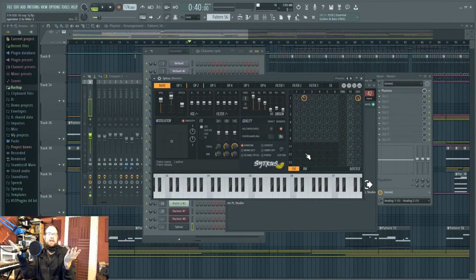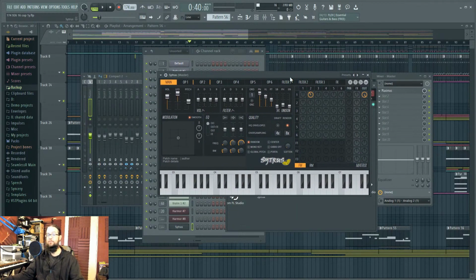It sometimes sounds okay and fun and cool, because sometimes it's just part of the sound you're doing, you don't even know it's happening, but you do notice it's happening because it's not harmonic. It's never harmonic. It's never the right numbers. And that means that the honest-to-God difference between analog stuff and digital stuff is this exact quality. And digitally, the version of the solution is to use oversampling, which makes the plugin run individually at higher sample rates so that it can do some work on those frequencies, so that when it comes out of the plugin, they're not there, or at least not as high or hard, and thus not doing the effect as much.